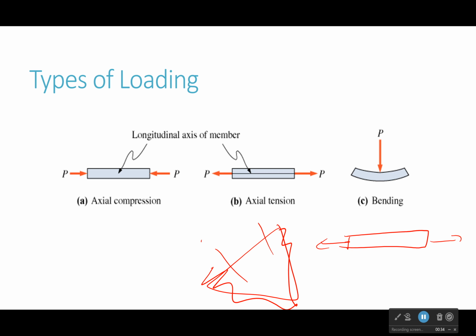But what is this called? Well, if the forces are pointing out, it's tension. If the forces are pointing in, it's compression. And as a note, compression is usually considered negative. That means in your free body diagrams, just always draw the arrows pointing away from the member. If you cut somewhere, draw the arrows pointing away from the member. Because when you solve for them, if you get a negative number, you just know it's compression, and you leave it as a negative number when you put it into the Moodle or something else.